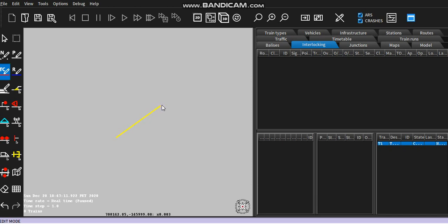So you will have to develop your whole network one by one into several paths, as many as you like according to your design, and then you will assign a track circuit to it for the identification of your train location. Once the track circuit is assigned, the next step is to assign a route, because on a certain network there might be a number of lines.